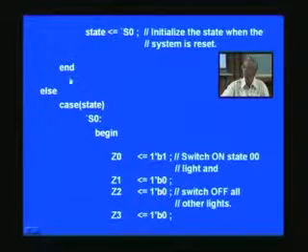Now what we have seen earlier in the earlier applications, so many else if used. Here we have only one if and then else, and here starts a case statement. It's similar to what we have already seen in the combinational circuit, and that depends upon the actual state, which is a variable here, indicating which state we are in.